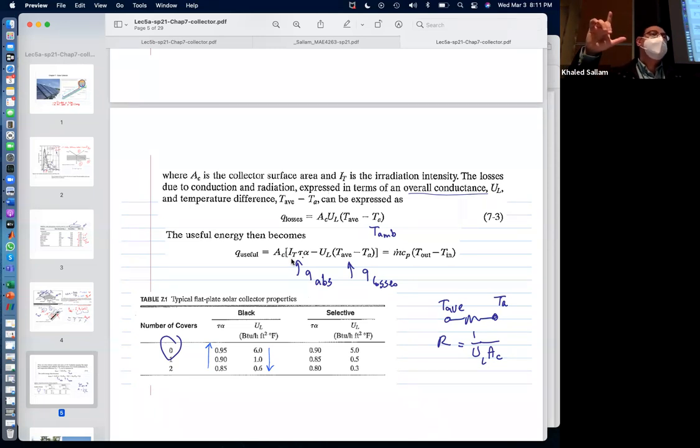Normal radiation, if you're going to make the plate tilted, well, normal, right? You are not going to put it horizontally, right? That's going to be less radiation. So you can get the incident radiation on a normal plate on March 21st. And that would be your I. So A multiplied by I, the area of the collector, that's how many watts. So watt per meter square multiplied by meter square, you get what?